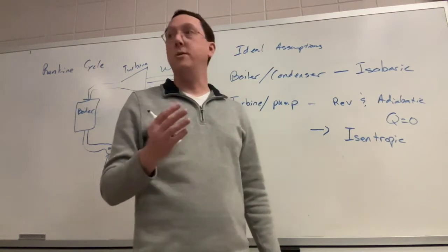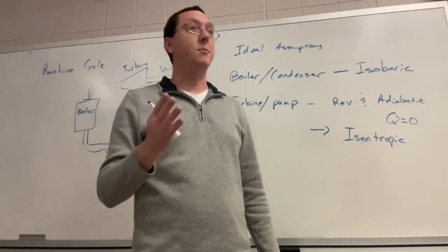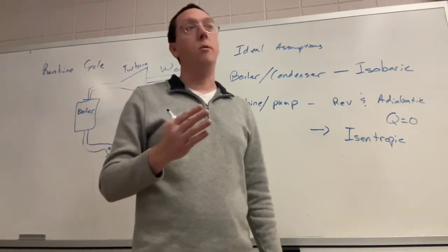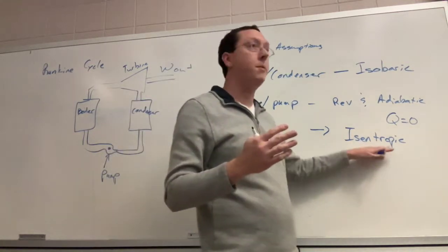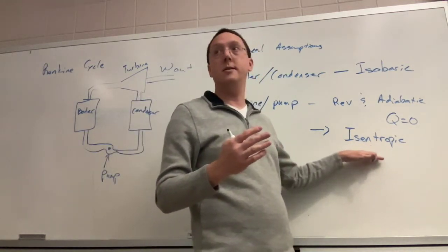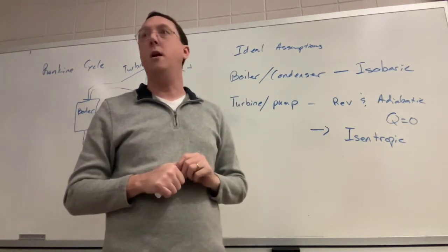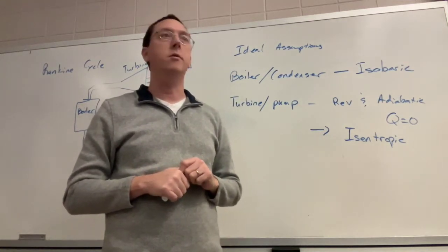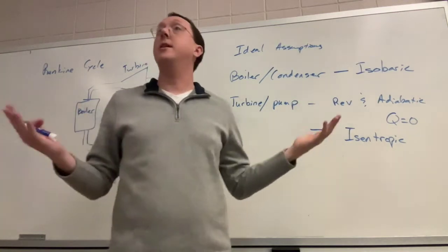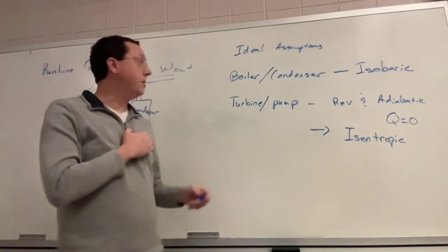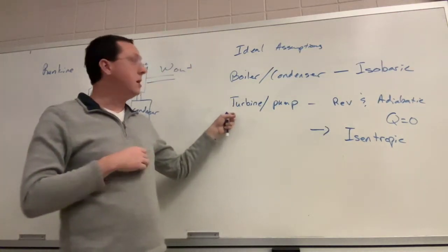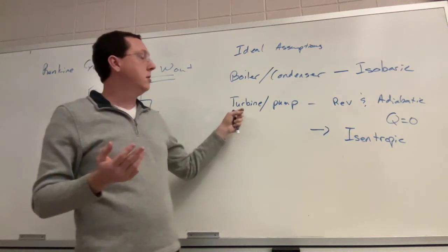And I don't usually worry about spelling. If it wasn't important, I wouldn't pay attention to it. This is important, okay? Isentropic, because it is entropy that's constant, as opposed to enthalpy. That's what you would assume if you had a nozzle or diffuser or a different device. So for these, the enthalpy will change in general.